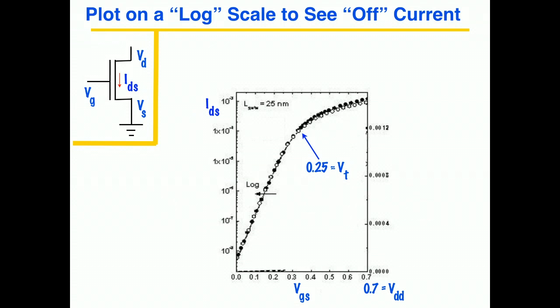When the gate voltage goes to 0, there's still some residual current through this measured or simulated device. Before we had that very flat exponential, that's a straight line here. And when we had that linear looking thing, it looks like that. Here's the threshold voltage at this point.